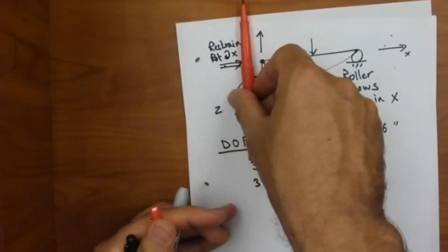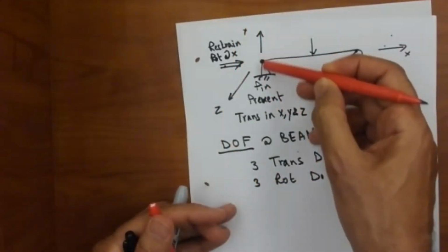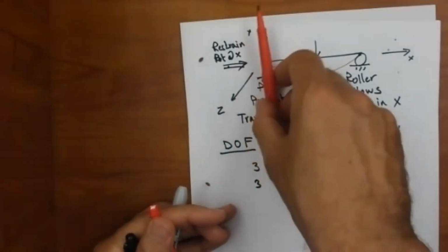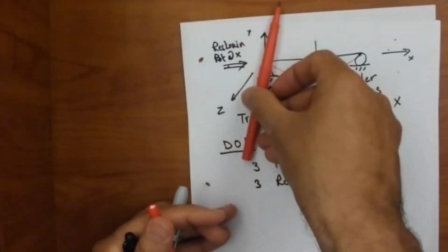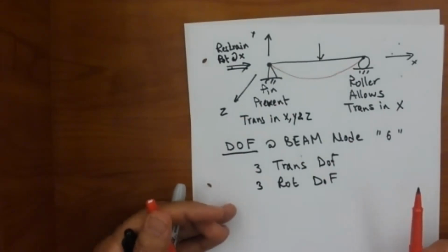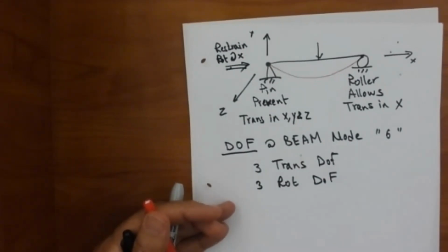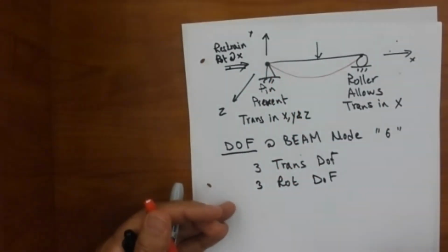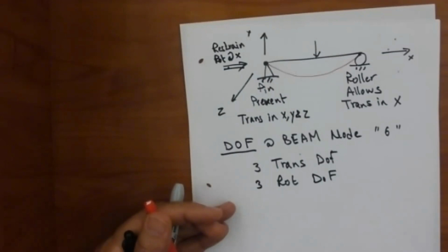But this face is represented by a point. So only a rotation would imply the rotation of the face. We do not have rotational degrees of freedom when we are using solids, because when I'm using solids, every point represents a point in real life, unlike this point on the beam element that represents a face. So please always keep that in mind.